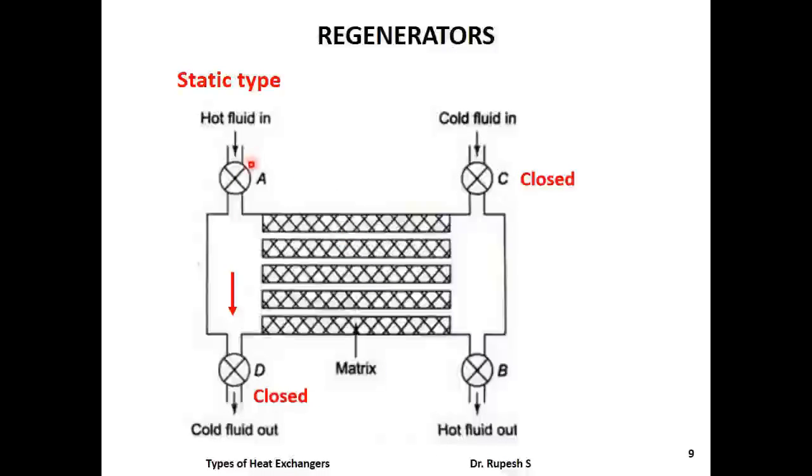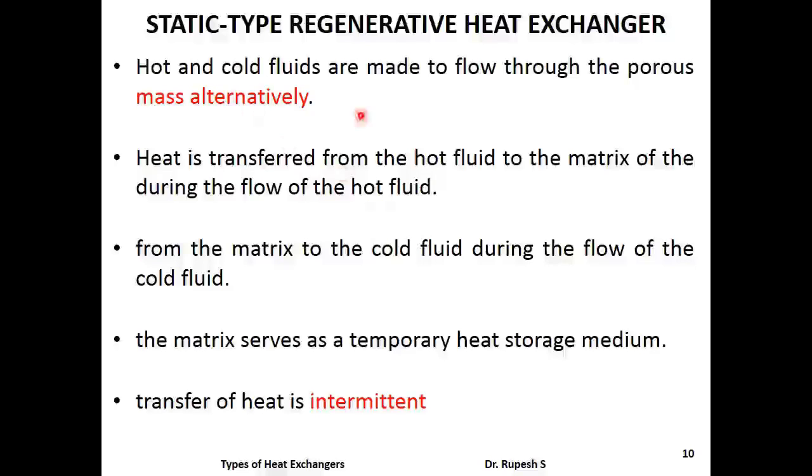During the first phase of the operation, hot fluid flows through the matrix in this direction and heat is stored in the matrix. During the next phase, cold fluid flows through the matrix and takes away the heat stored in the matrix. Valves of hot and cold fluids are operated to achieve this particular working. Due to this nature of operation, heat transfer associated with static type regenerator is intermittent or non-continuous. These are the points pertaining to static type regenerative heat exchanger.